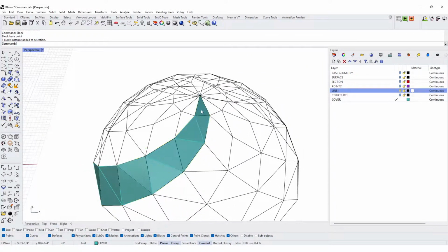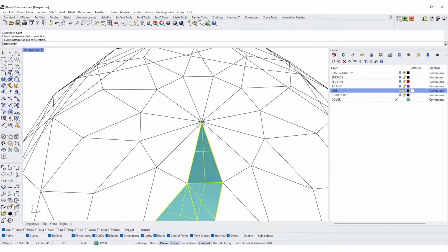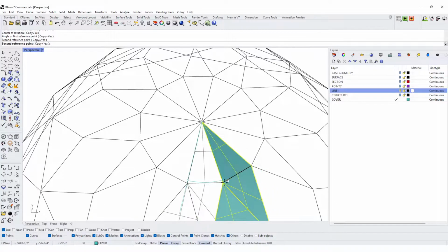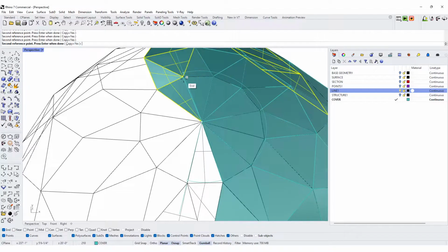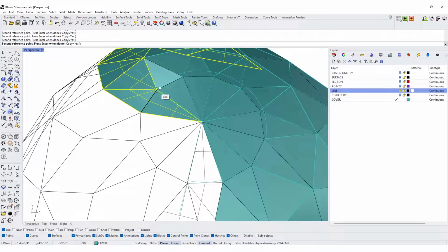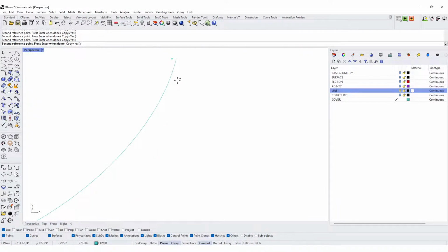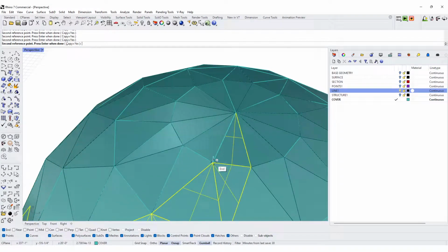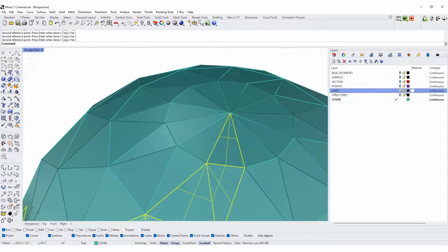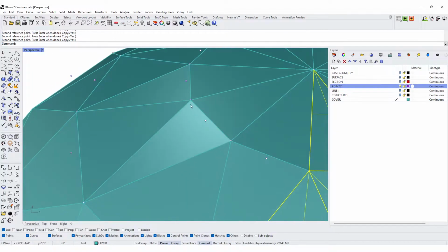Now with this, that we've created that block, now let's do polar array. Now we can do polar array, do 1, 2, 3, 4, 5, or I can take this, do rotate, copy, yes, and just make sure that I have those endpoints on so we can go from here and work our way around. So this is where there could be some mistakes introduced. That's why I always try to snap to maybe not even lines. It would be even better to use some of these points.